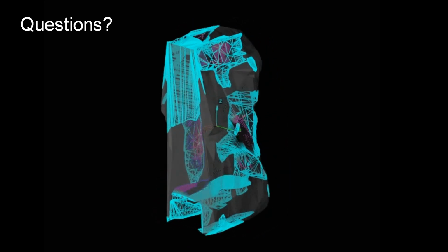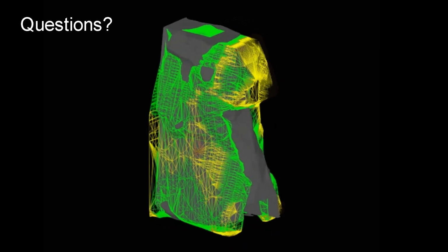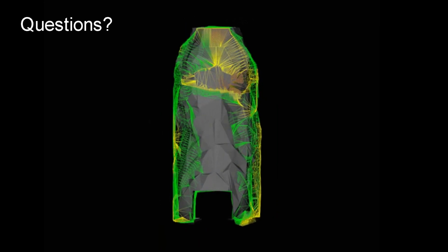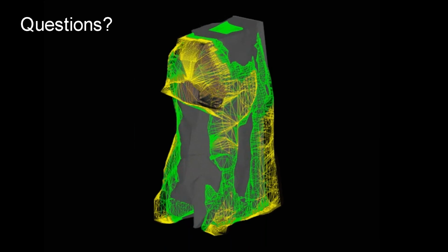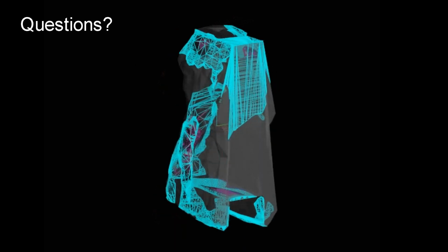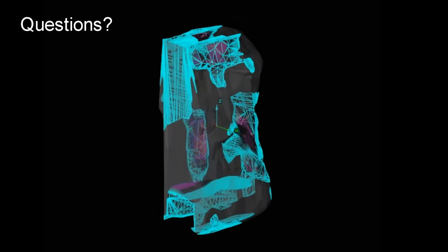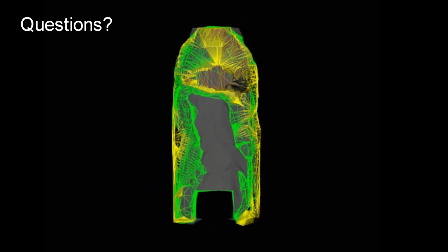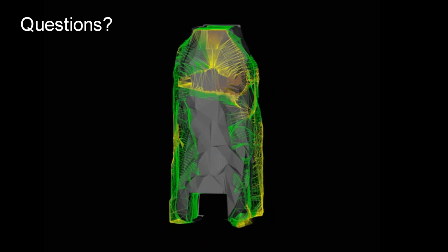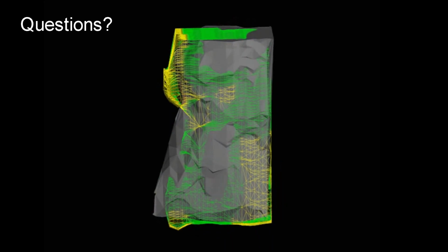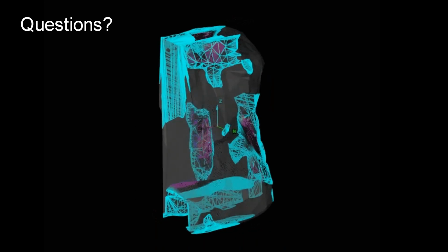No, absolutely. And then I think I'll end this session because we're coming up to time on the last question, which is a bit of a bombshell. What's one of the best ways to mitigate overbreak in development headings? Oh boy. Well, I think that a lot of it comes down to blasting, but without good drilling going into it, we're not really setting ourselves up for success. So I think the biggest thing that I've seen is perimeter control. Having the right pattern, the right sized holes, the right timing or delays to really maintain those clean faces.